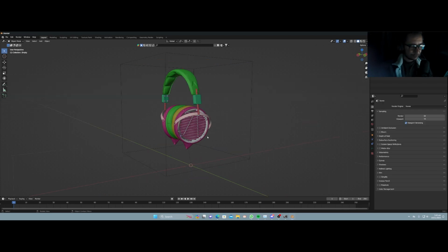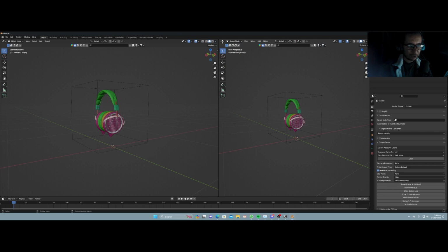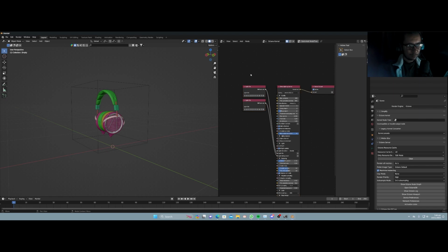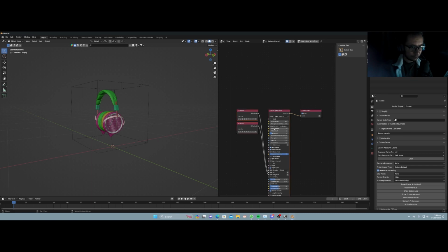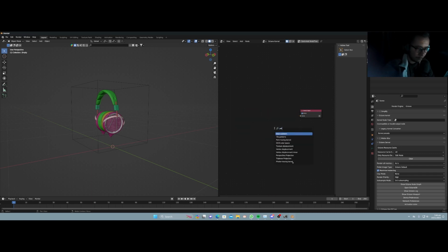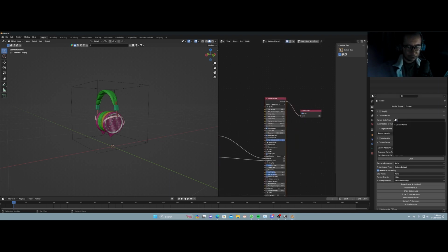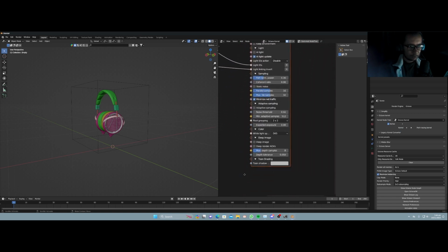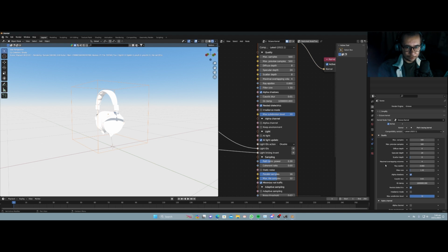So I've been getting a few questions. Hey, I downloaded Blender Octane, but it's not working for me. Well, what's the solution? First of all, go into Octane, split your screen, go into Octane kernel, and add a quick node tree. So by default, it gives us direct lighting kernel. We don't need that. We want the path tracing. So let me just put it in, and I'll add this over here. Boom, we got the kernel loaded up. So yeah, now if I go over here, it's working and I have all of the samples over here.